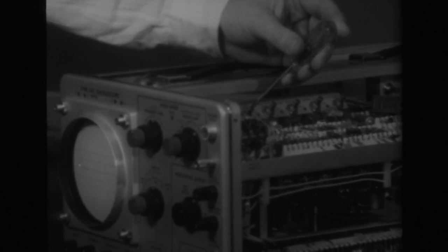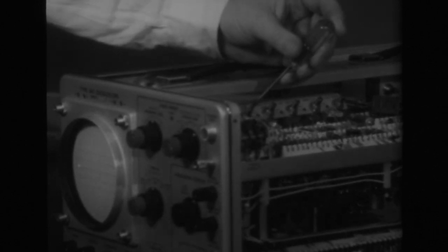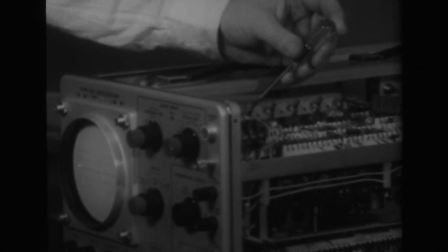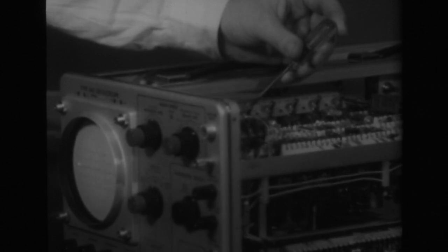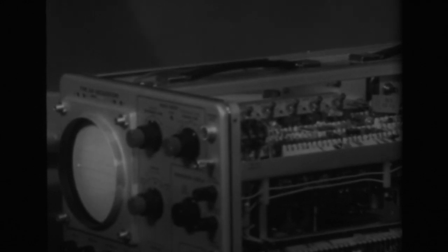And then turn the control clockwise to again cock the bistable multivibrator, and again come very slowly counterclockwise until the sweep has just triggered. In other words, has just produced a trace across. And as soon as you have found the point where the sweep has just produced one stroke, remove the screwdriver. The control is now properly adjusted.